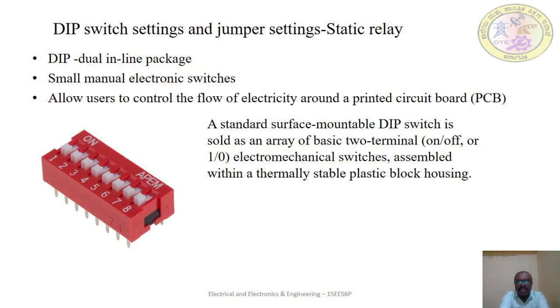DIP switches are usually useful whenever selecting a particular device function requires multiple switches to be toggled to achieve the right output mode. A standard DIP switch may consist of 1 to 10 or 16 or even more toggle switches, rockers, sliders or rotary switches mounted on a single small block.